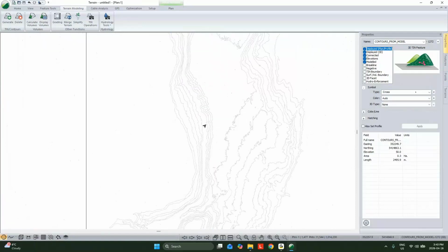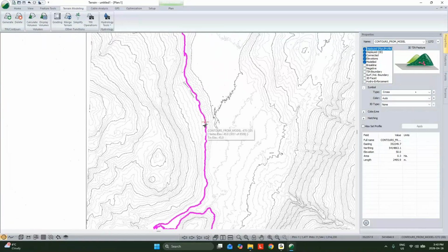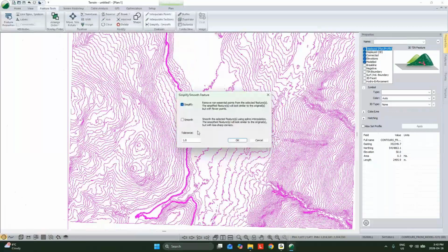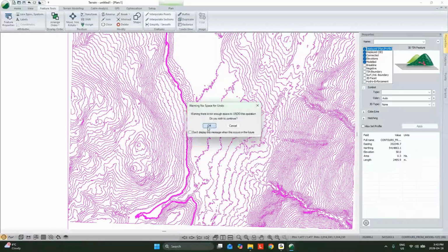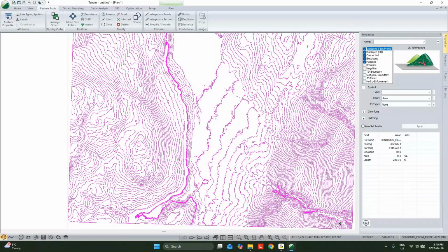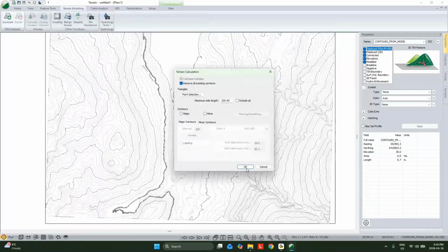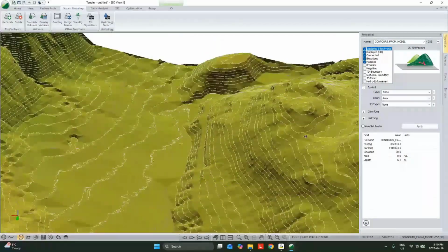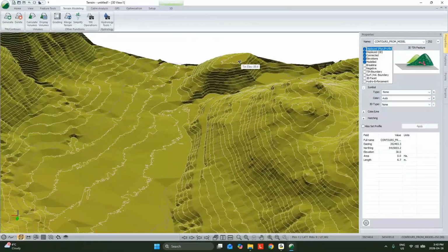So if we wanted to make this even lighter, we could use that simplify functionality. So we're going from 1,000,000 points down to 100,000. So nice and light, but we can make it lighter. We're not going to be dealing with just the fact that it's contour data and we don't have points where we'd probably like to have points to model. So that is a few tricks and tools to working with big data sets. I'll pass it back to Erin.